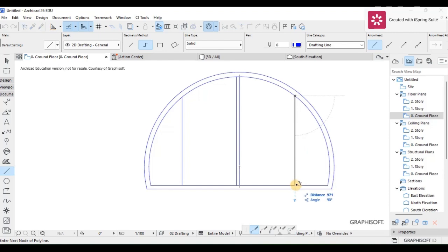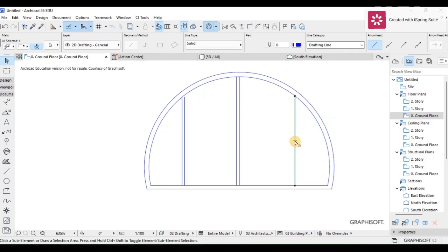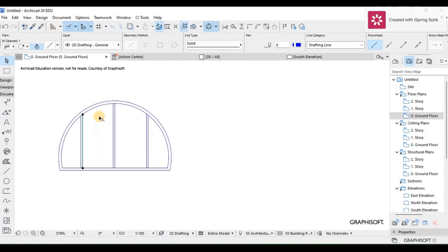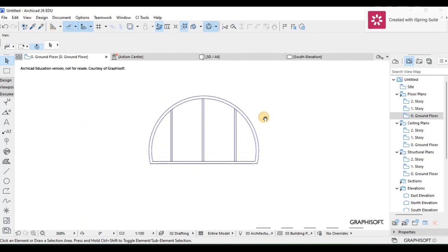So with that done, now you can offset. You can just drag a copy of this or offset it to create another frame here. Maybe let's just create it on the inside, maybe let's say 30, and then I can enter, and then do the same with this one. Control Shift D, and then 30. Just dragging a copy and entering. So I'm just going to extend this so that they can meet my corner frame, my outside frame, and create some kind of window like this.